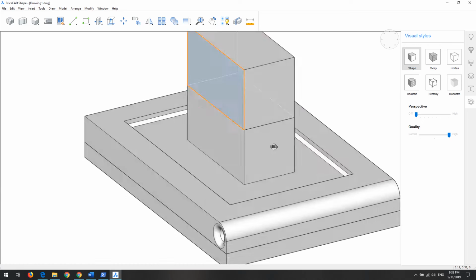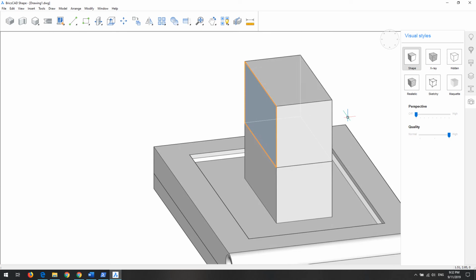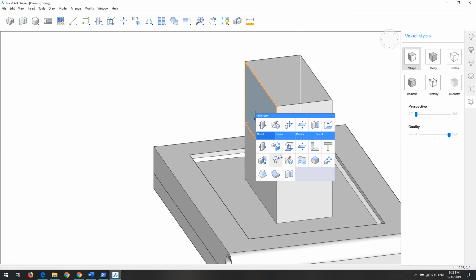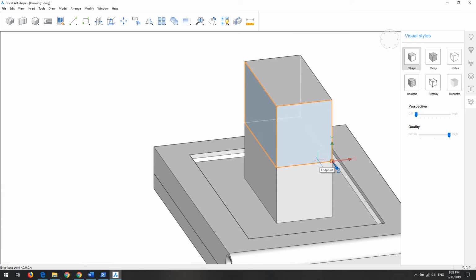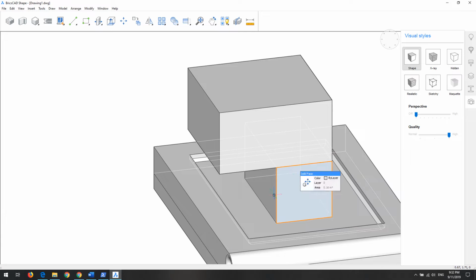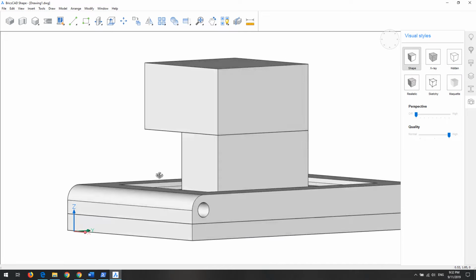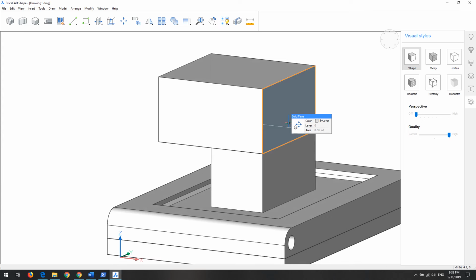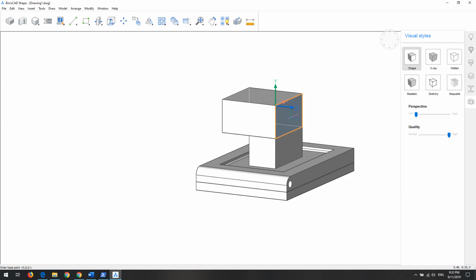I'm sure drag is just going to move the selection. Let's select this face. Let's do it manually. And then we want to move it. The origin is this point, but it's not moving. Yeah, so we moved that much. And also we want to move this face. Let's select the origin, and we can type in a value or use the guideline.